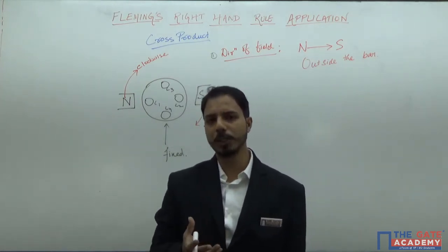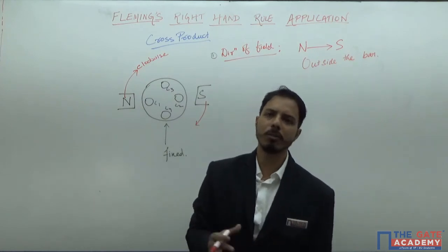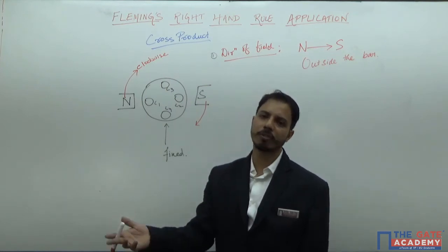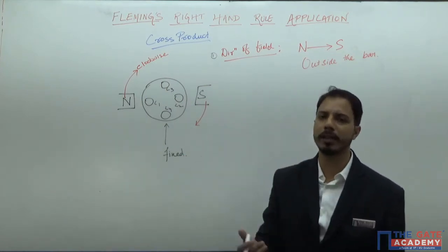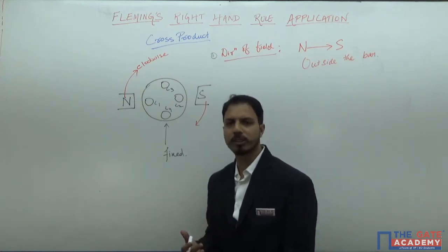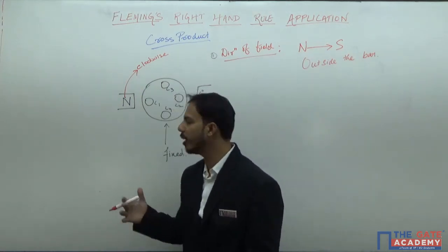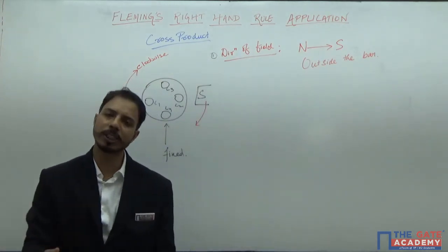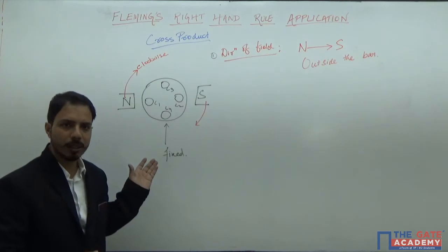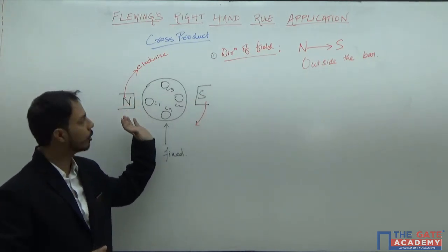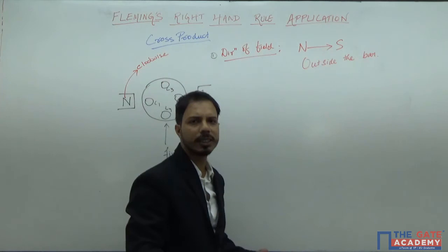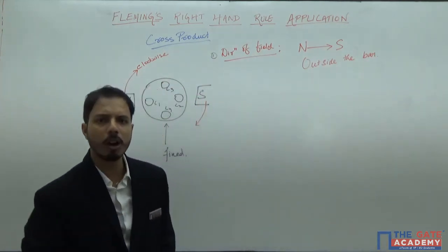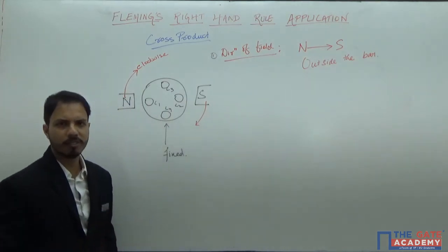Now when EMF is induced, then what will happen? Then current will be flowing in those conductors. Now once current flows in the conductors in presence of a field, then force will be applied in the rotors of the induction motor, and the induction motor starts rotating along the direction of the rotating magnetic field. So if the rotating magnetic field is clockwise, my rotor will experience a force clockwise. Okay, so this is the principle of working of an induction motor, three-phase induction motor.